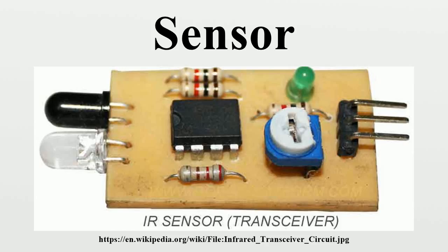The encapsulation of the biological component in biosensors presents a slightly different problem than ordinary sensors. This can either be done by means of a semi-permeable barrier, such as a dialysis membrane or a hydrogel, or a 3D polymer matrix, which either physically constrains the sensing macromolecule or chemically constrains the macromolecule by bounding it to the scaffold.